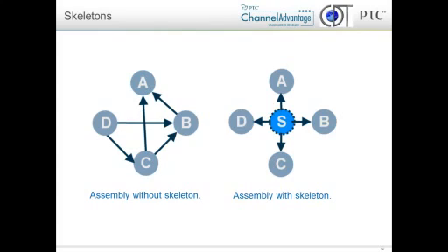On the right, you can see each component is directly mated to the skeleton, so I don't have to worry about if something changes in the mate of C to B, is that going to affect the way D mates to B and then back to A? If everything's mated directly to the skeleton, individual components can be moved and maybe even fail regeneration if someone changes them, and that's not going to break my overall assembly.